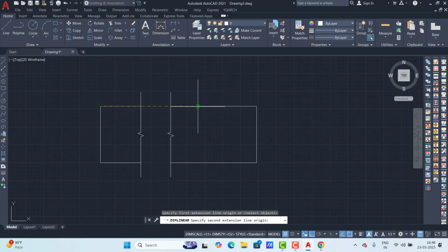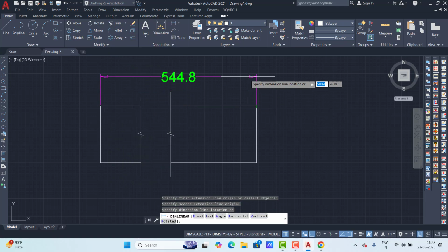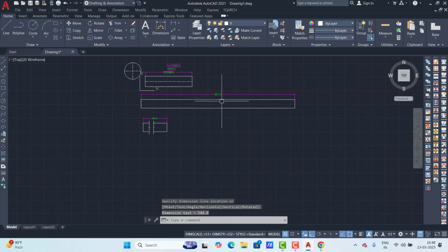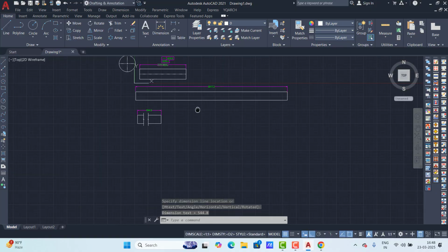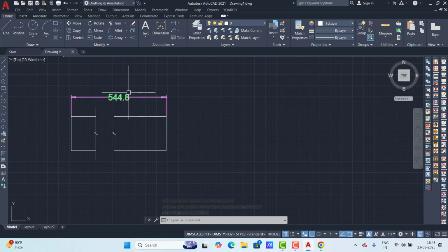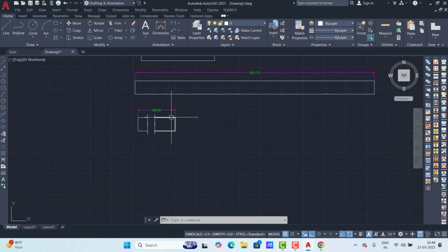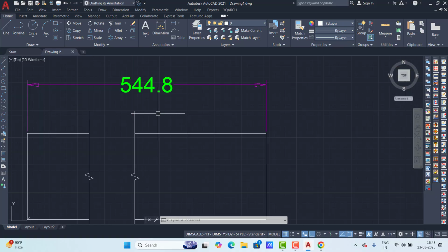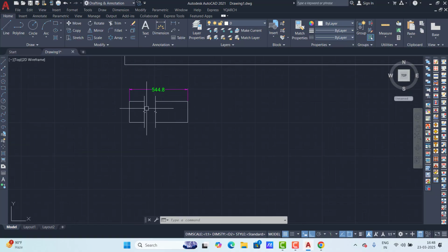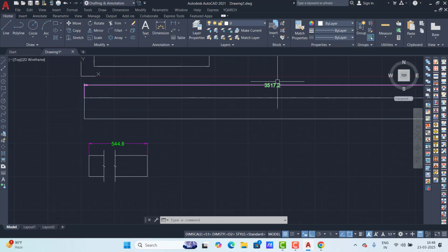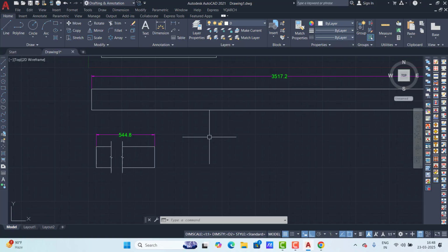Okay. So here you have to understand: this direction we always use 30 degrees. This direction we always use minus 30 degrees, and this direction we use 150 degrees. So remember: this direction 30, this direction minus 30, and this direction 150. So just go to Oblique, select this one and press Enter. Type 30.